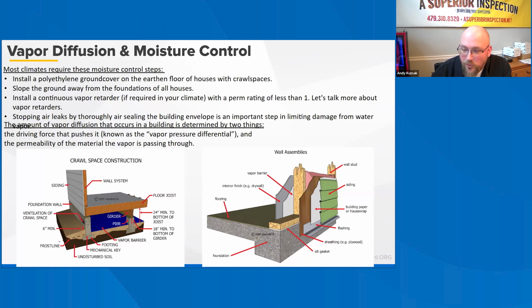Vapor retarders only retard moisture due to diffusion, while most moisture enters walls through fluid capillary action or as water vapor through air leaks. Water vapor can also be carried through building components by diffusion, driven by pressure and temperature differences. Vapor diffusion can be impeded by use of a vapor diffusion retarder.